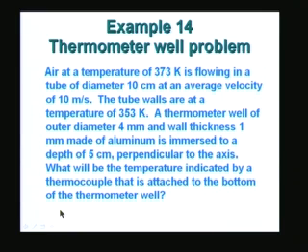and take an example which is very common in practice. In fact, I have already referred to this earlier, that we use a thermometric well or a thermo well in applications where we are measuring the temperature of fluid which is flowing inside a tube, and we would not like to have a contact between the measure sensor which we are going to use, maybe a thermocouple or maybe some other thermometer.